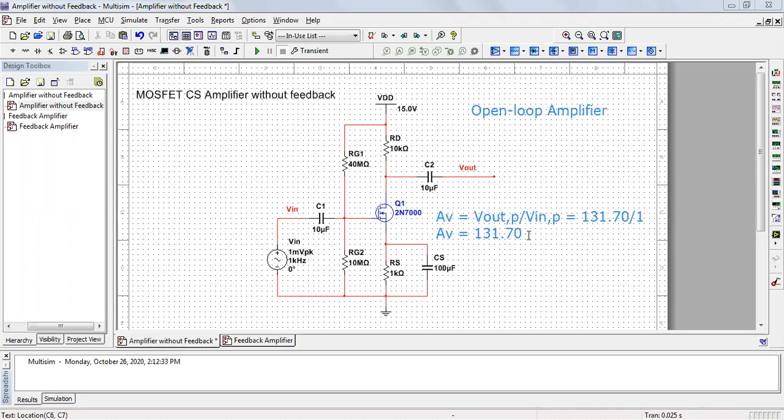In an oscillator, we want to increase the signal, whereas in amplifier applications, we want to reduce the open loop gain of the amplifier to our desired value. Say, for example, I have an application and I want my amplifier to have a gain of 1000 only. The open loop gain is 1 lakh.